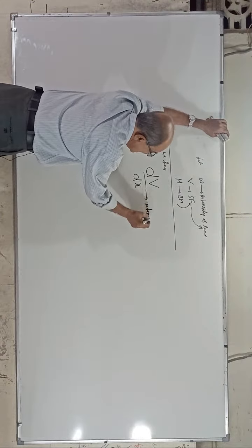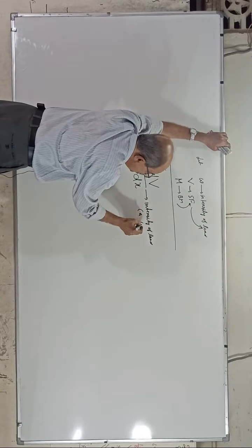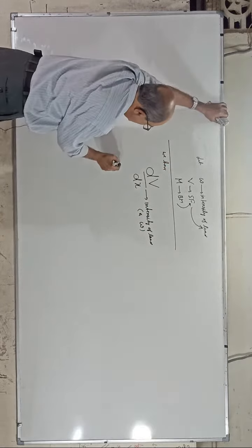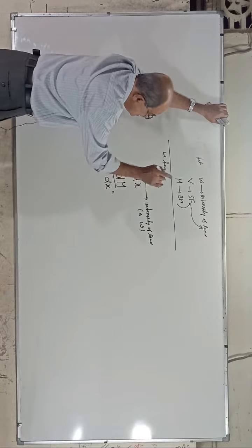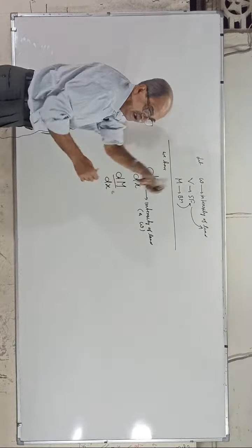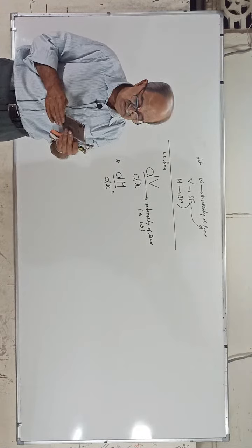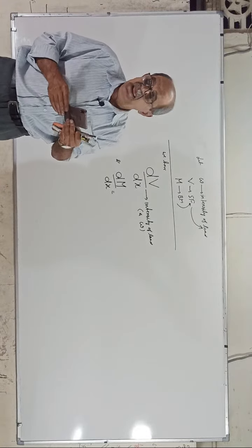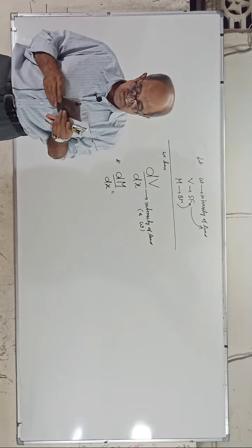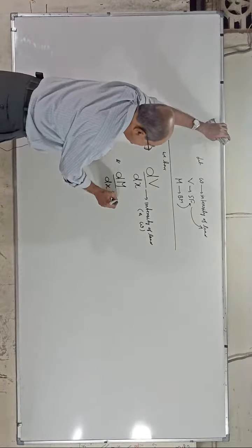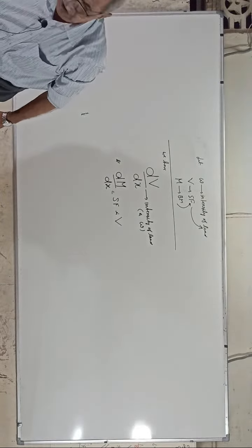Some principles I am telling, I won't repeat. Intensity of load, that is w. And anybody can tell, what is dM by dx? Tell me, at least tell that one. Slope I will tell you later, one minute. dM by dx is the shear force, that is V. Therefore, I will write something now, a very powerful concept.